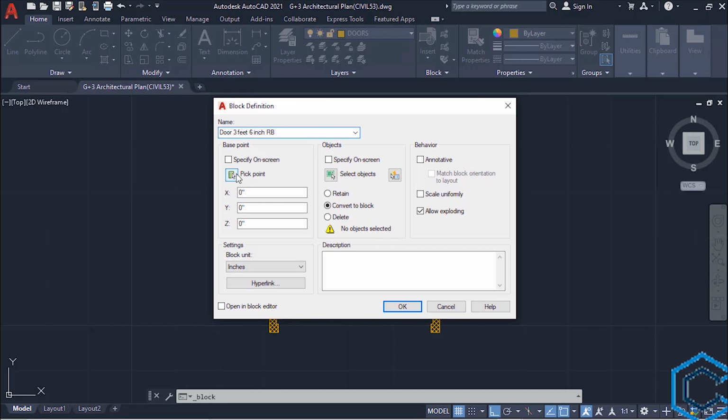Before placing the doors, we have to trim the walls. Come into the plan. Try to place the doors at corners of a room so we can utilize the area of a room to maximum. We have 2 inches space at the back of the door. 1 inch will be taken by plaster, and in the rest 1 inch we will place the magnetic door stopper. Now let's make the door openings, but we need to change the layer from doors to wall.